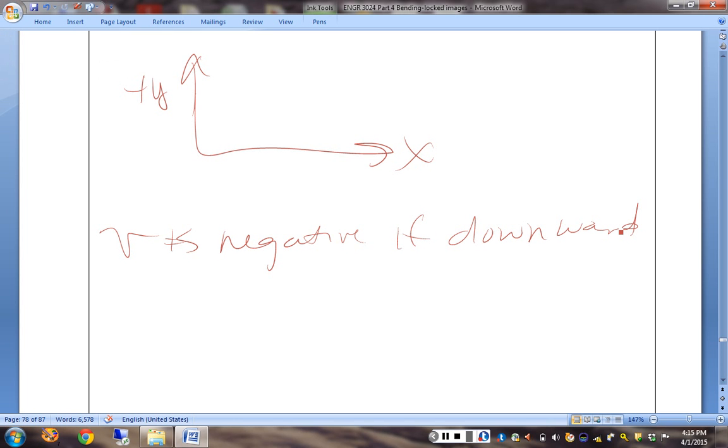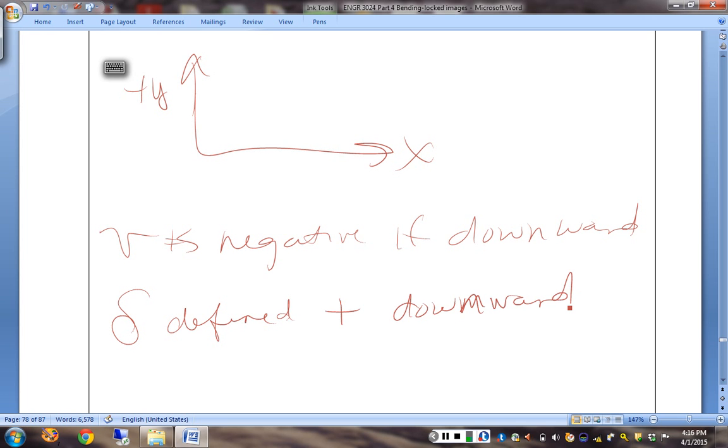Different people who tabulate these things can use a different convention. One important one that you might run across in your engineering world is the FE manual. It's a very common reference tool. Instead of defining deflection to go along with the plus y, they define a quantity delta, which is a deflection defined as positive downward.